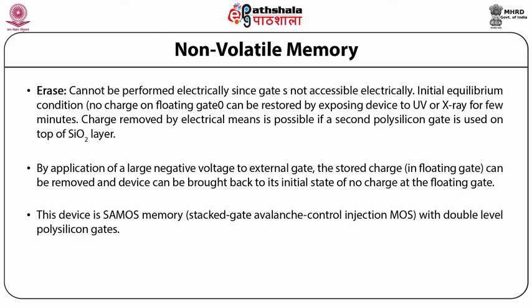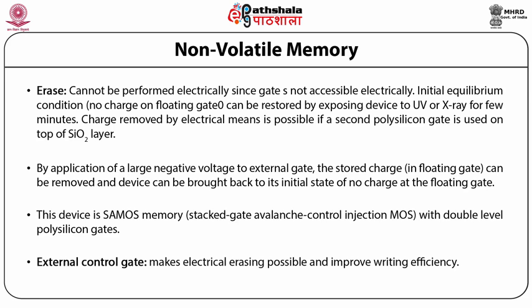This device is a CMOS memory, stacked gate avalanche injection MOS with double level polysilicon gates. The external control gate makes electrical erasing possible and improves the writing efficiency.